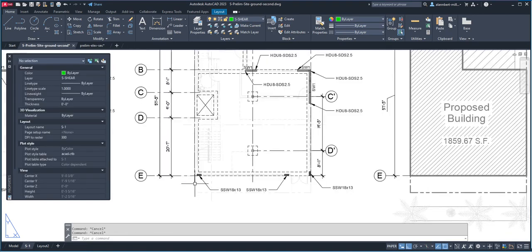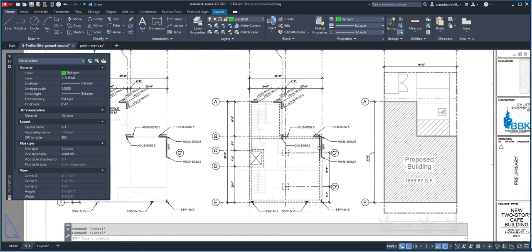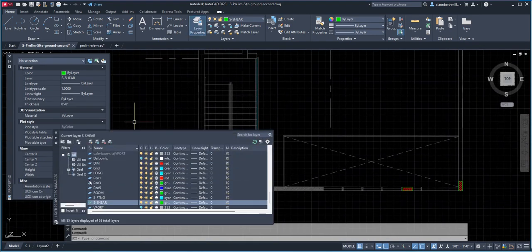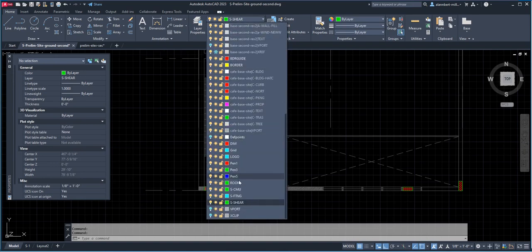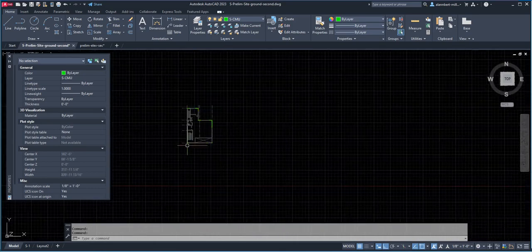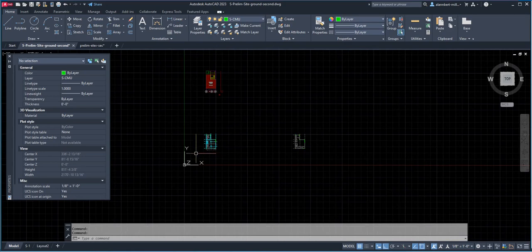And so we're going to do the same thing as we did for the shear walls. We're going to the model space and we will create a new layer, and we're going to call it CMU. We're going to still leave it as a green line, and we're going to use that as our new wall. And know that the walls have to extend by this much here.